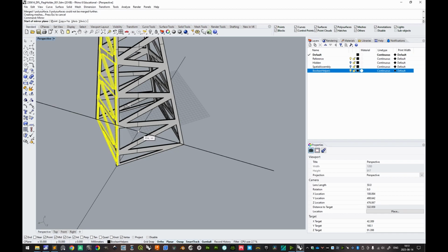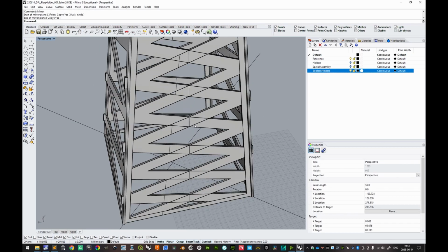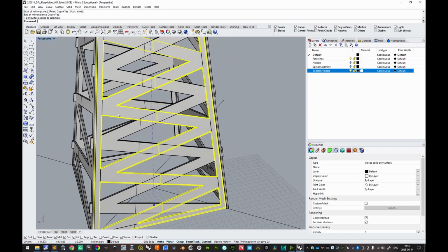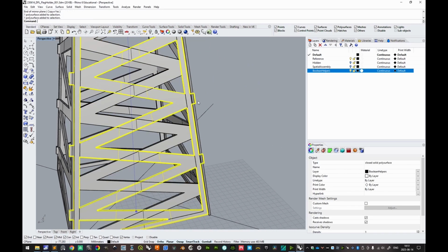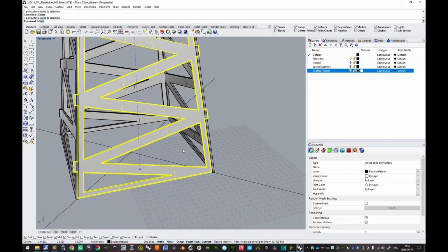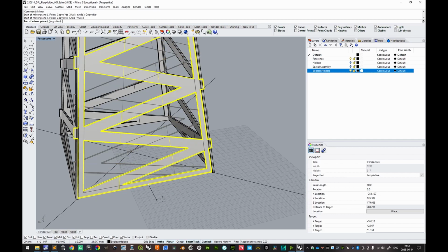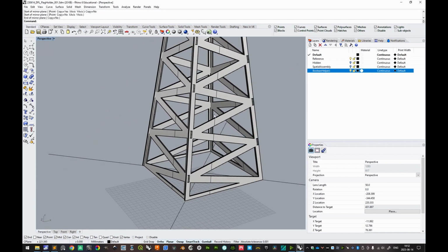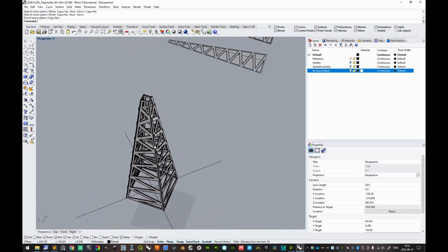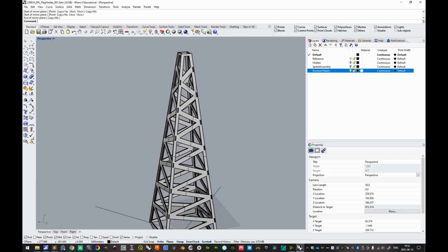Mirror this from the center point, copy yes. Like that, and it should be mirrored again, so let's make sure that we select the one that we don't want, this one without those ones. Like that, and then we mirror this. Let's make sure that we don't copy it then. All right, very good. And the next step should be to do a Boolean difference, of course.